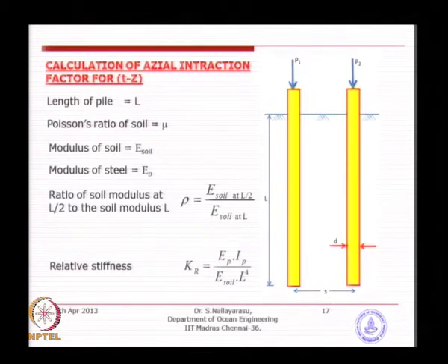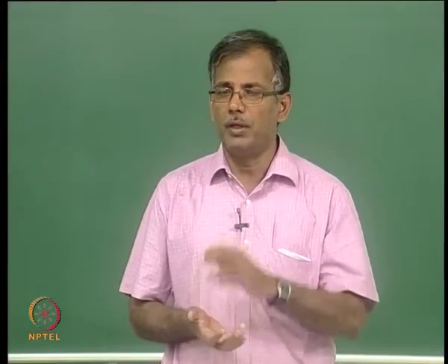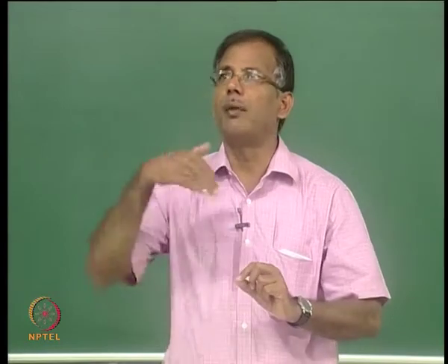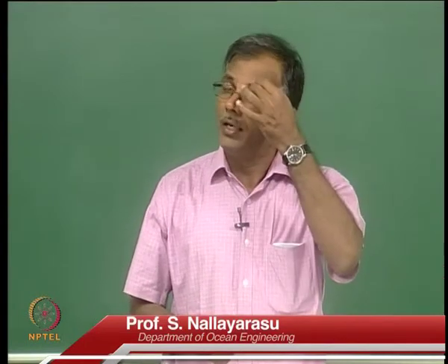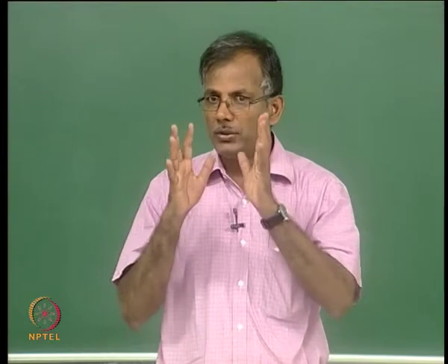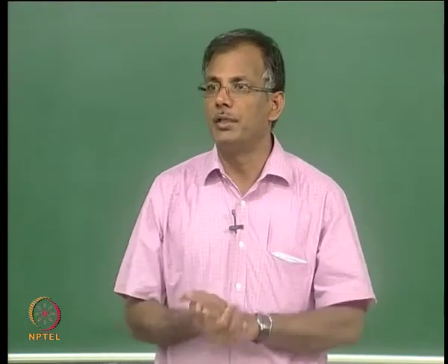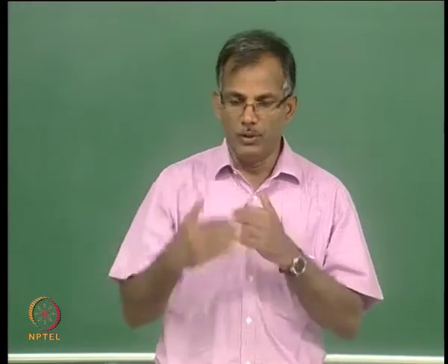In fact, we were talking about when we are doing the t-z curve for various soil. If you are developing a t-z curve at a particular location, what happens to the previous layers is the most important thing. So, most of the procedures developed earlier always talk about a single-layer methodology. Even the API equations we have just discussed do not discuss how you treat multi-layered soil. So, we have to be cautious.